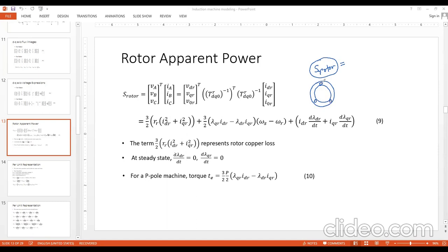This is an induction machine. So what we are doing instead is supplying some electrical input to the three-phase coils of the stator, and then we have, of course, some air gap, and through the air gap the energy is being transmitted from the stator magnetic field through electromagnetic induction. The energy is transferred to the rotor coils, and ultimately the rotor would get the torque. So the rotor would get some induced electromagnetic torque, due to which the rotor would start to rotate.